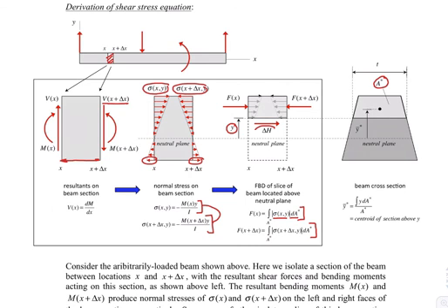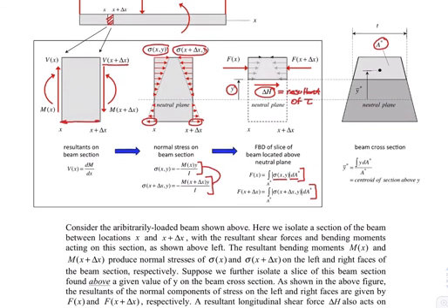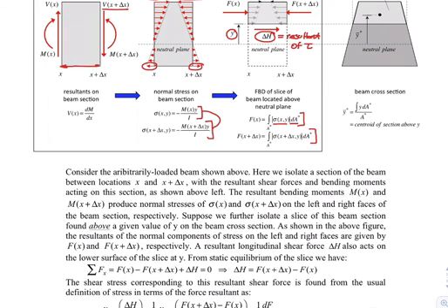And this delta H, that is the resultant of that shear stress. Okay. Well, two things we need to do. First thing we need to do is relate delta H back to the F's. So as I take that FBD above, if I sum forces in X, F of X on the left side, F of X plus delta X on the right pointing to the left, plus delta H, we see that this